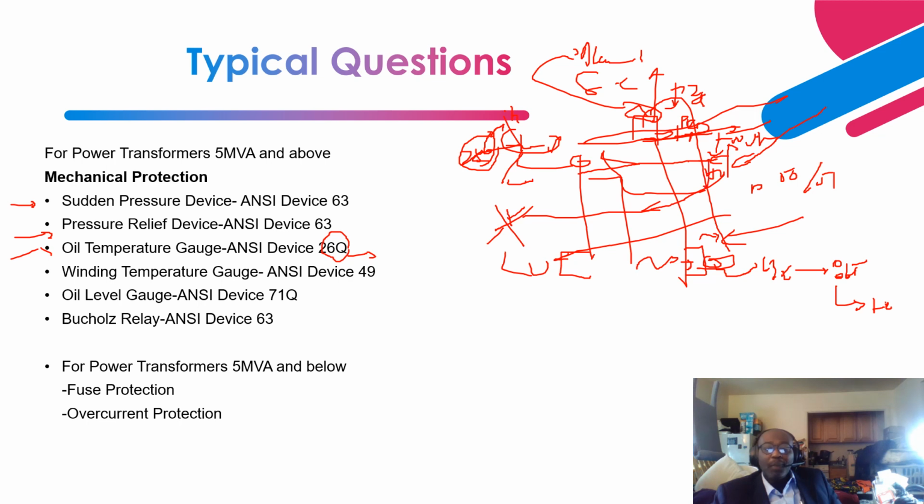If it drops, you see that it's going to come down. It's been calibrated so that the changes from the top of the oil correspond to inches, based on, let's say, a 1 degree rise or fall in temperature. That's how the calibration is done for this oil temperature gauge.